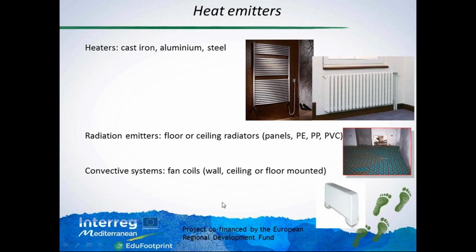Those three different types of emission are characterized by different water temperatures. The heaters here are normally driven by high temperature water. What does it mean? The temperature starts from the boiler at about 70 degrees and comes back to the boiler at 50, 60 degrees.